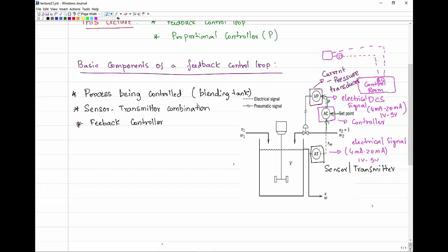The control valves are mostly pneumatic valves, and they operate by adjusting the air pressure supplied to these valves. The signal out of the controller is sent to an IP, current to pressure transducer, which is then converted into a pneumatic signal in the range 3 to 15 psig. The pneumatic signal is then sent to the control valve to move it.